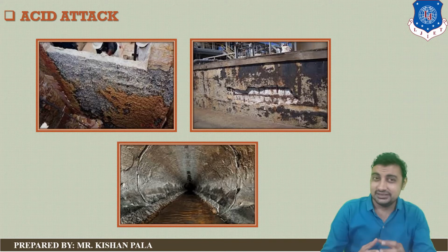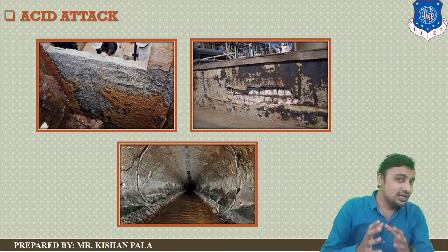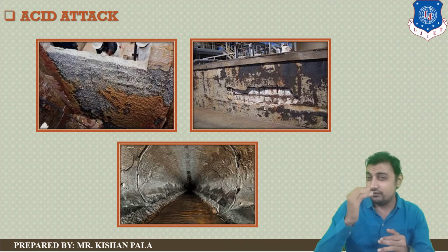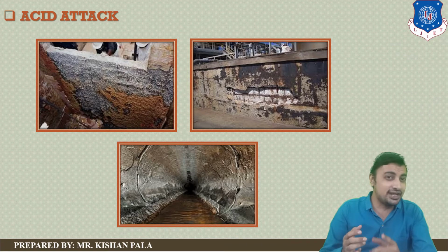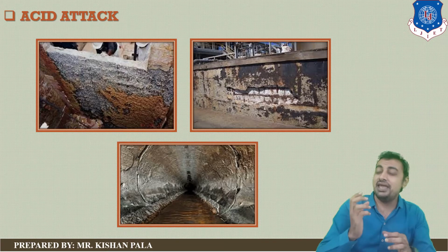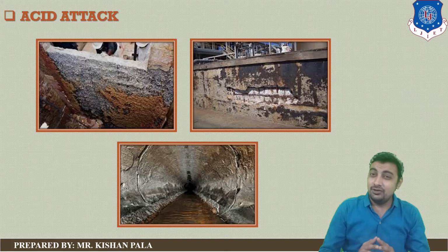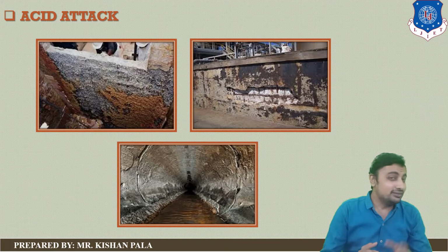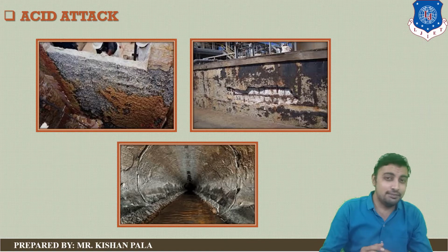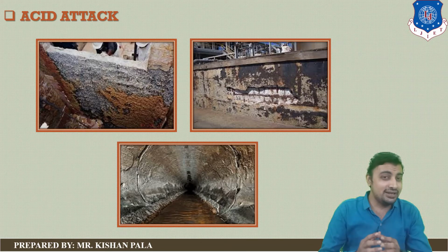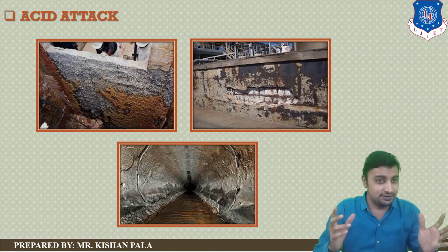In practice, acid attack occurs at pH values below 6.5, but the acid attack is severe when the pH value is below 5.5. At a value below 4.5, the attack is very severe. Under acid attack, cement compounds eventually break down and are leached away.